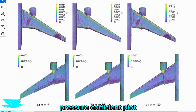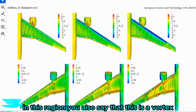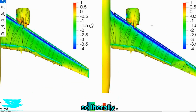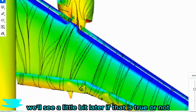Looking at the corresponding pressure coefficient plot in figure 8, there are streamlines tracing towards the fuselage in this region. They also say that this is a vortex that is actually being created by the cutout of the leading edge slat to accommodate the engine. So literally this cutout here, where the engine is attached to, that's creating vortices and it's coming up over. We'll see a little bit later if that is true or not.